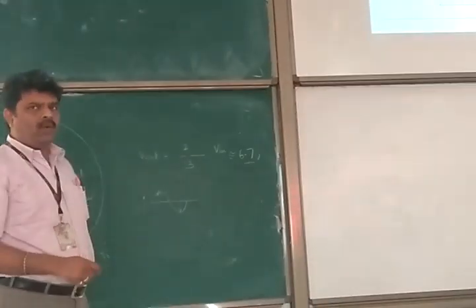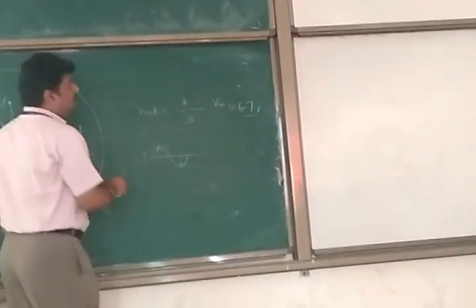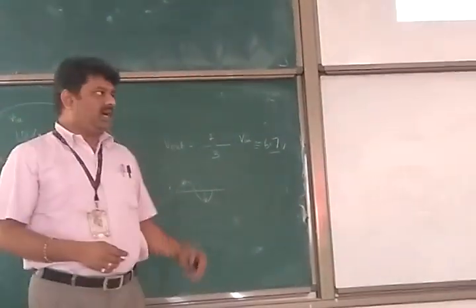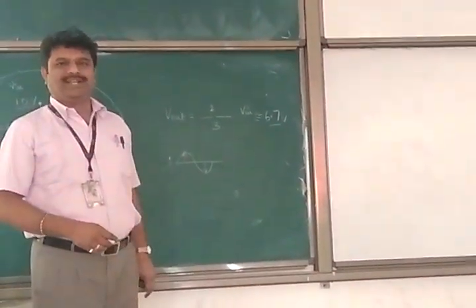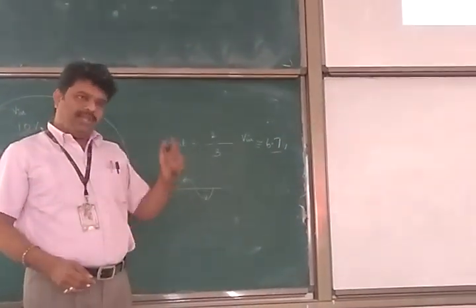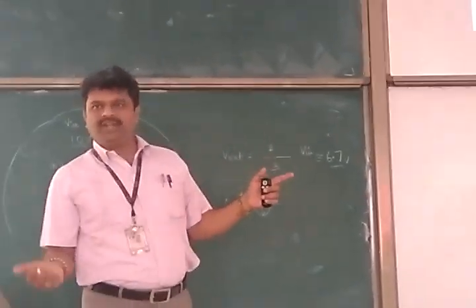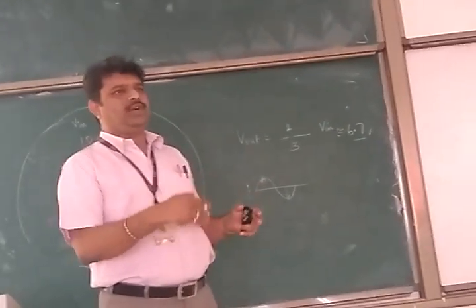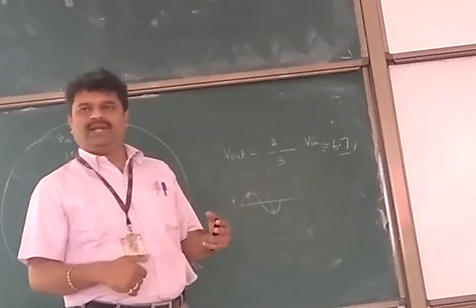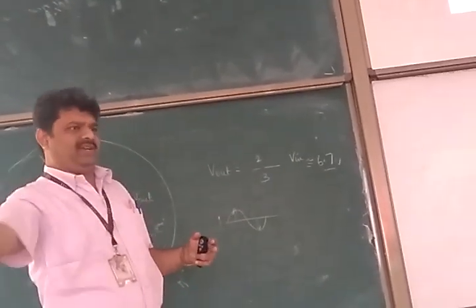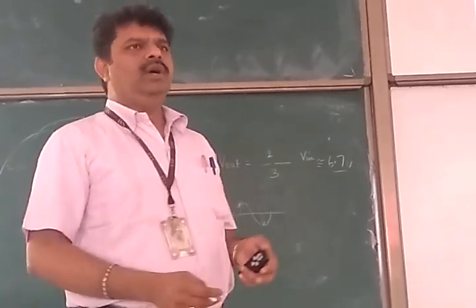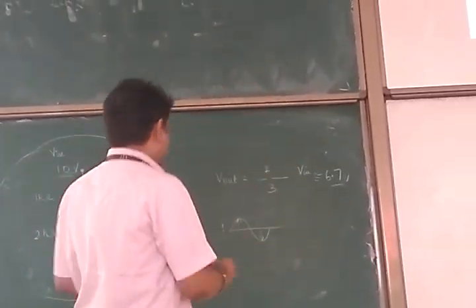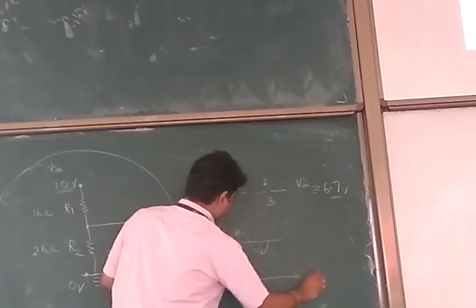Okay. So now, you can achieve that in 2 ways. Sir, I don't want this voltage divider circuit. No problem. You give a positive 5 volts and negative 5 volts. Anything between 0 to positive 5 and negative 5, you amplify and you get it. There's no problem.